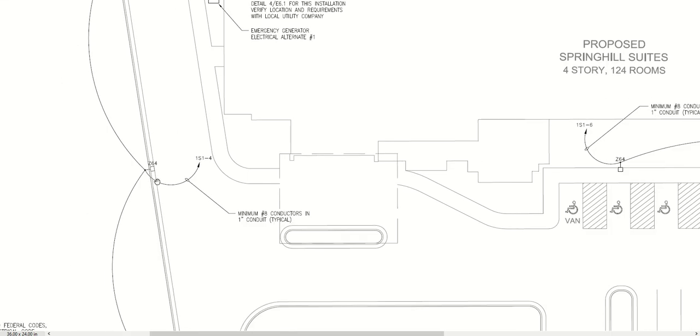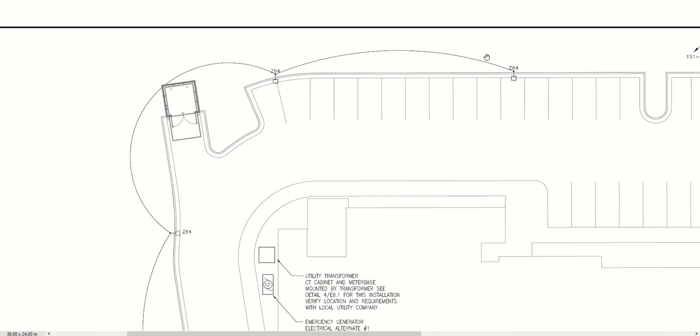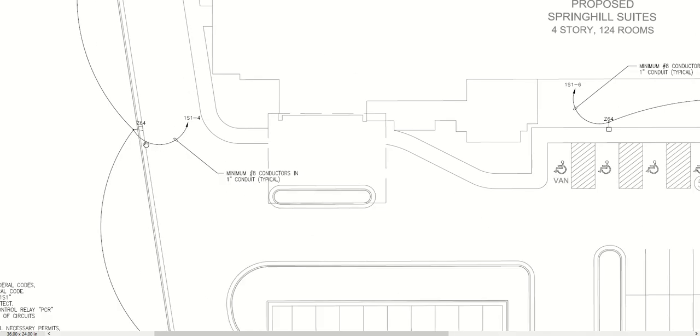And while we're not talking about lighting, we can go ahead and talk about that we have to power the lighting, and so these would be circuit lines showing how these light fixtures, these are pole fixtures, are connected, and then this is a home run signal showing that we run it to this location, then we run this back to panel 1S1, it'll be circuit number 4. And because these are such long runs and we are a little bit worried about voltage drop, we upsize the conductors. Normally we'd run number 12, which we talked about in the conductors lecture. In this case, we'd want to run number 8.